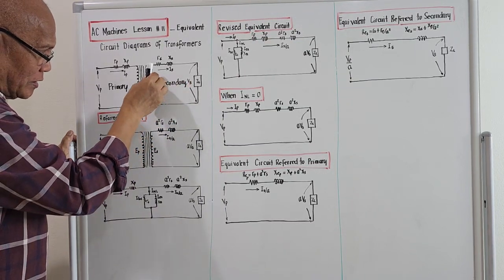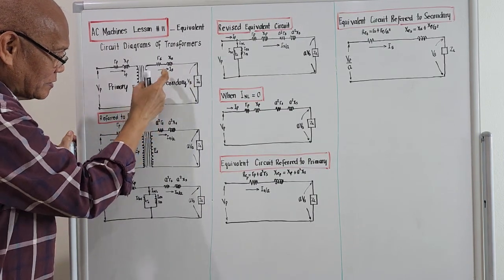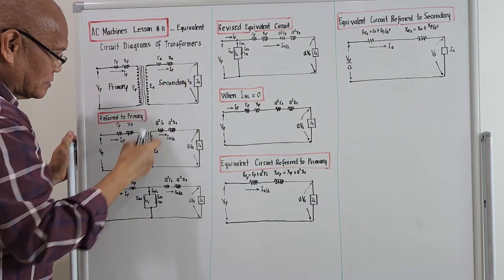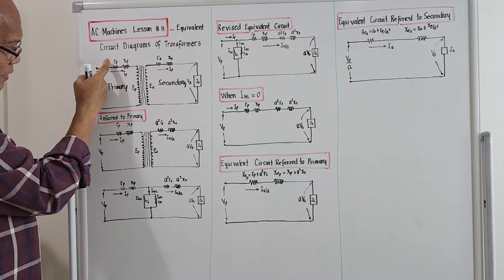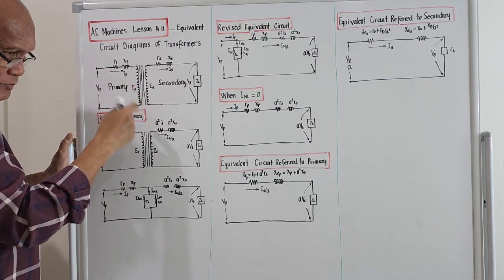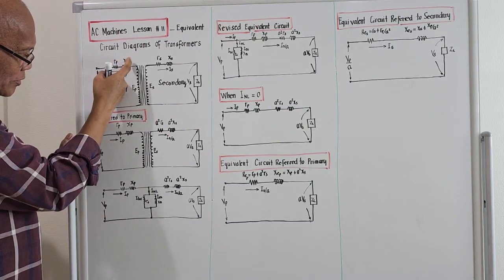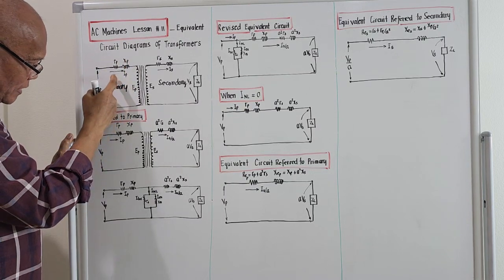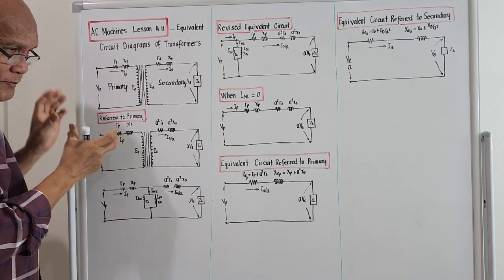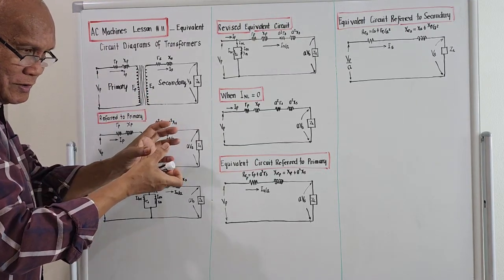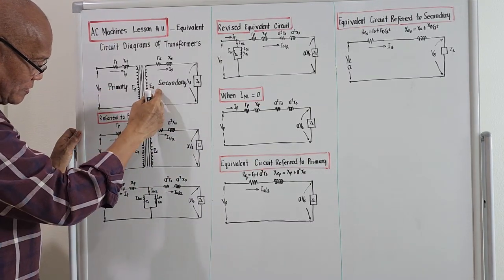As you can see, all the terms on the secondary are with the subscript S. On the primary side, it's the same. The resistance of the primary, due to the resistance of the windings, is designated small letter r with the subscript P. This is X with the subscript P. Current I sub P, the current coming from the secondary side, not primary side. And the applied voltage on the primary is designated capital letter V with subscript P. So this is the primary side, the secondary side.